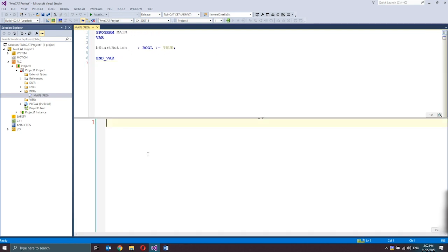The body is written in one of the IEC programming languages, which include IL, structured text, SFC, function block diagram, ladder diagram, or CFC. In here, in the main program, the implementation language is structured text by default, but TwinCAT PLC Control supports all IEC standard POUs. And if you want to use these POUs in your project, you must include the library standard.lib in your project.